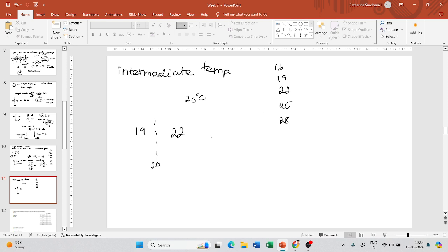So if I take 22, if I'm going to request a bitumen whose PG grade is 22, what will happen? In my field, my temperatures can go below 22 also, up to 20, and so the bitumen cannot satisfy my requirements. Till 22 the maximum criteria of 6000 kPa is reached. Now when I go below 22, the stiffness of the bitumen will be even higher, and so my bitumen cannot satisfy the fatigue criteria requirement.